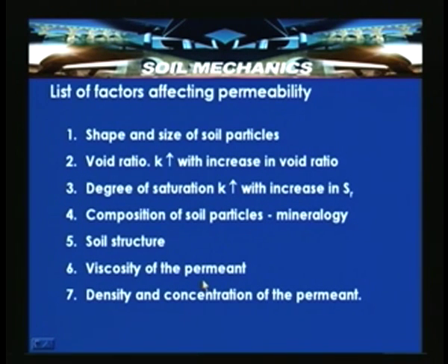And we also discussed, based on Taylor's equation, the relationship that k is proportional to d e square, which indicates that with an increase in grain size, an increase in the permeability value can be seen. That is, if d e is the effective particle size, a large effective particle size can have a larger permeability. So, that is what we discussed as factors affecting permeability: the effect of the grain size.